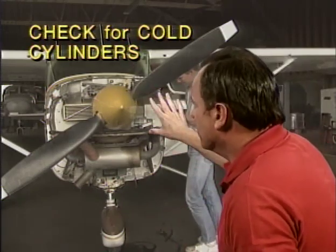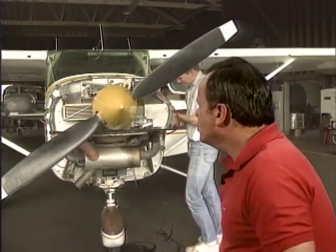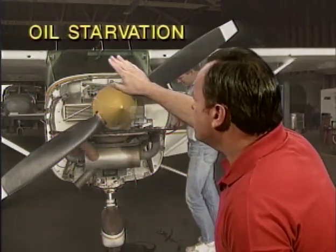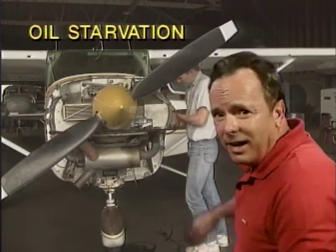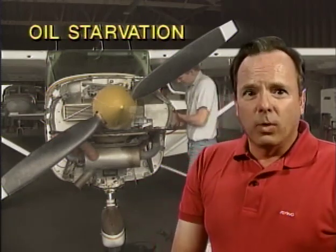Now, if a reciprocating engine is operated at high power settings before it's warmed up, they want you, Mr. Super Mechanic, to know what's going to happen. And the answer is you might have oil starvation of bearings and other parts. You might, in fact, ruin that engine by operating at high power before it's warmed up.